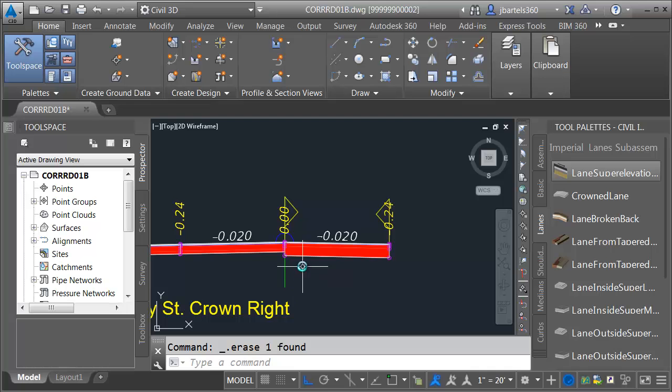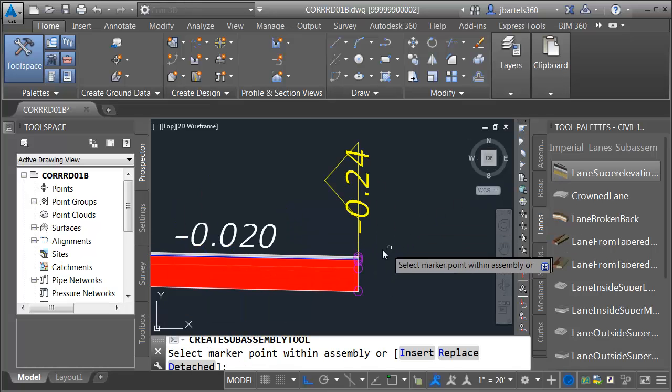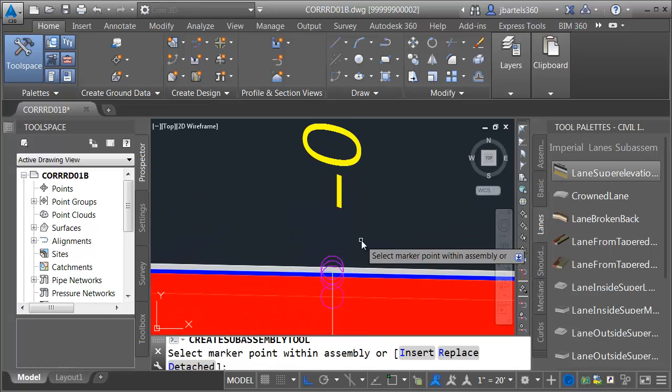What I did here, this lane is considered part of this group. Had I just placed this lane to the right side of the assembly, it would have been considered part of the right side group. And as this lane pulled over, they would actually cross here. By making this lane part of the left side group, when this lane pulls over, this lane's part of the same group, they're all going to go together. Let's add one more lane. I'll snap this to the outside.